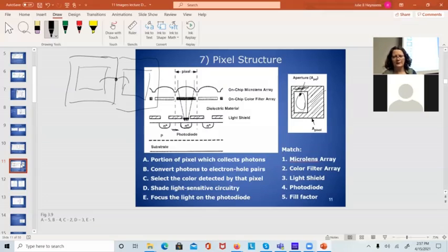The reason for building my 10 micrometer pinhole camera with George Simmons was that we wanted to scan across here and look at the light collected from here and from here as we're scanning across, and make sure that there wasn't a dip in the middle. And what we got is when you add the sum of the two pixels together, you've got a constant light across there. So we called that 100% effective fill factor. As you put more electronics in the pixel, the fill factor goes down. You're going to get a grainier image because you're going to miss some of the light in here.